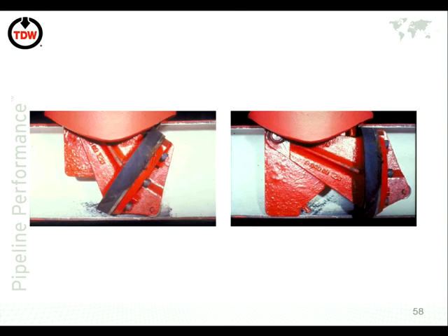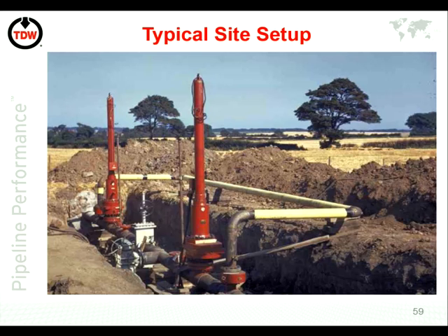So again, back to that picture I showed you at the beginning, hopefully it makes a little bit more sense now, in the sense that this is the pipeline that they want to do some work on. This is probably the valve, or the offtake, that they want to carry some work out on, certainly the work area. So what's happened here is this is 2 stopples. So there's been 2 fittings put on here. We've hot tapped through there and we've inserted stopples. So we've isolated this section. Some small fittings you see there, that's where we've released the pressure.